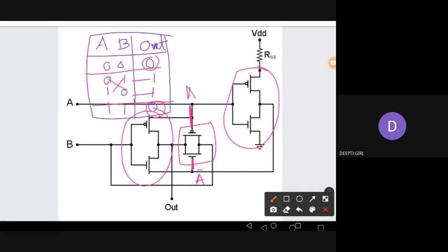Okay. Although these questions are simple, you need just patience to analyze which is on, which is off, and see the short circuit and the output value. And there's one extra resistance which I have not given to you yesterday. That is just a current control resistance, right? So that is a resistance put to reduce the current from the voltage source, to reduce the power dissipation.